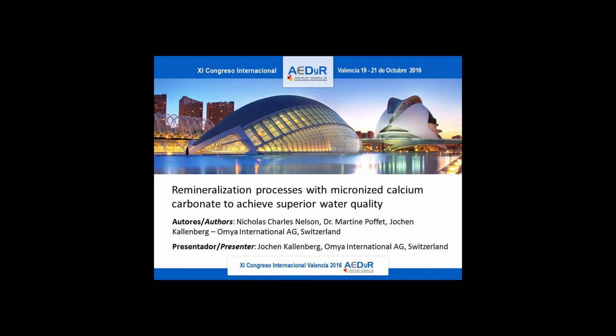So I think this part of the desalination process is regarded very often as a less important part of the complete desalination process. But as you have seen in some of the presentations before, post-treatment and remineralization of water is not only key for health, it's also key for agriculture to have the right mineral composition to avoid these SAR effects, sodium absorption rate, deficiency problems. And so that's part of my paper I'm presenting here.